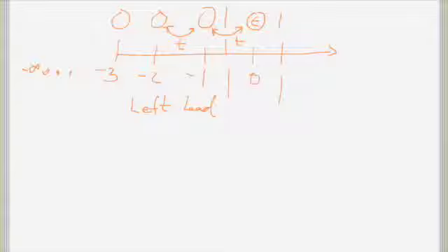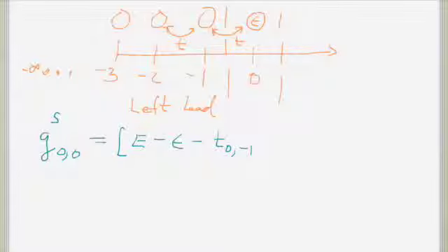So the device consisting of one node, my device Green's function, which is also my surface Green's function, is going to be equal to E minus H_D of the device, which is now just like in your homework, just epsilon, minus T_{0,-1} G_surface(-1,-1) T_{-1,0}, whole thing inverted.